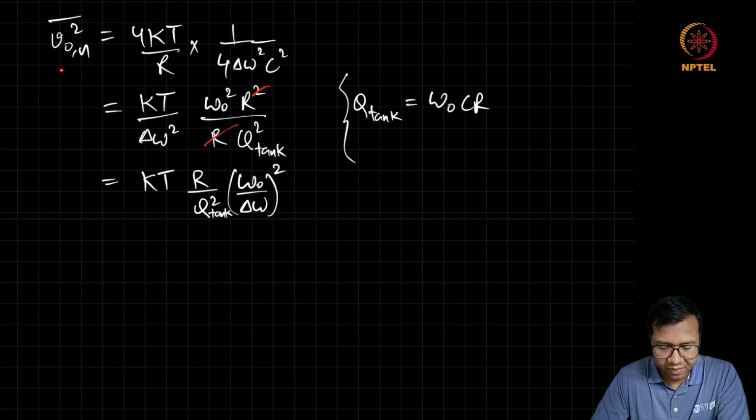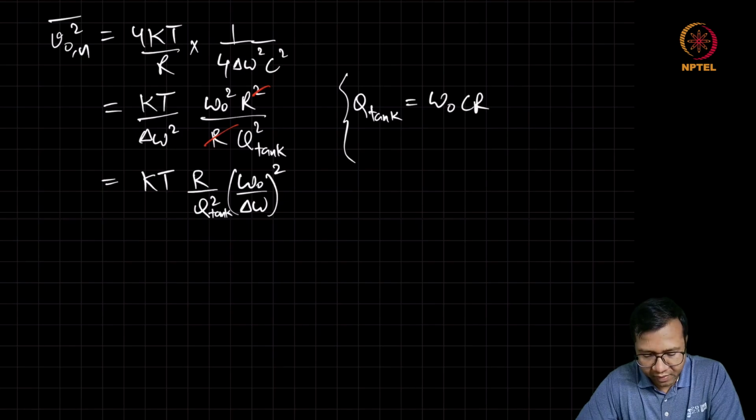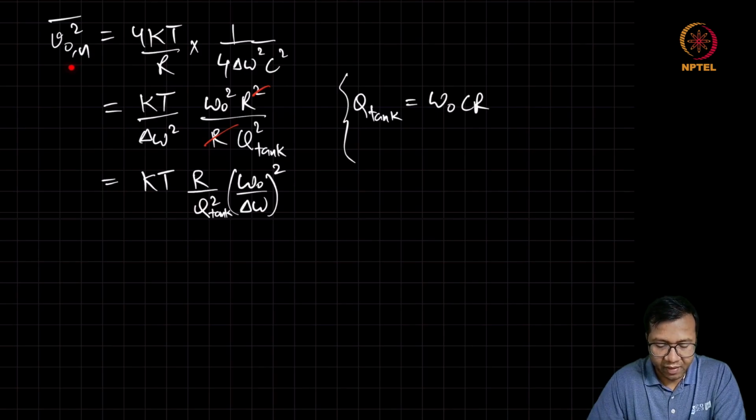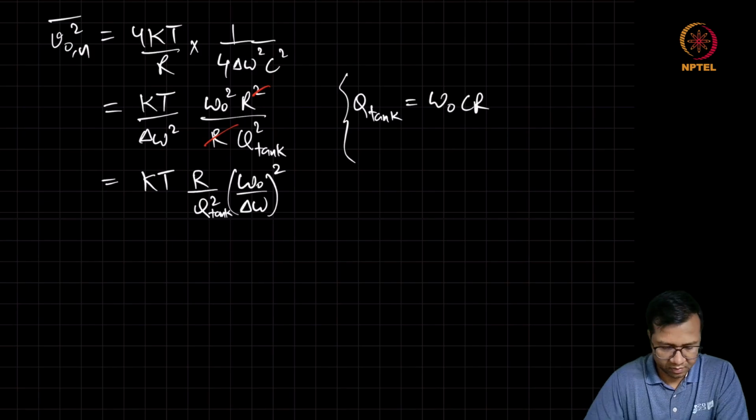So we understand that this is the voltage noise PSD at the output of the oscillator, and the oscillator is already oscillating with some amplitude. So to understand how this additive voltage noise is going to affect the phase noise of the oscillator, let us quickly find out a useful result which relates the effect of additive noise to the phase noise.